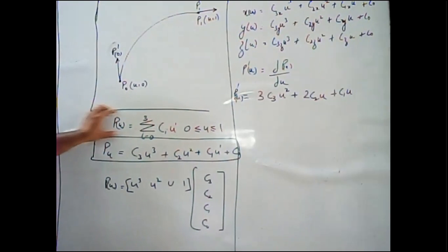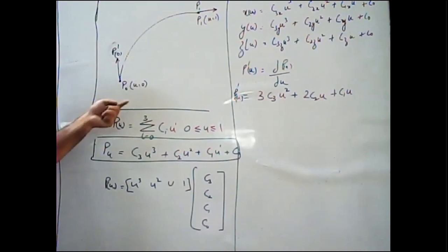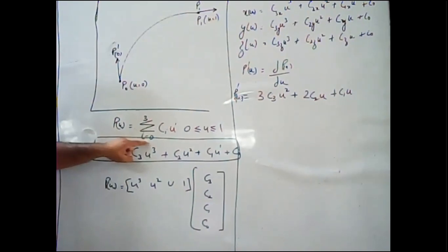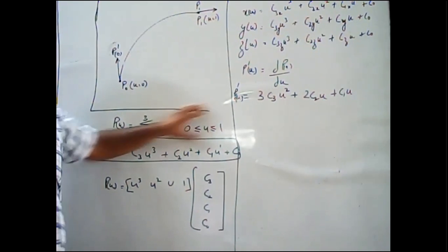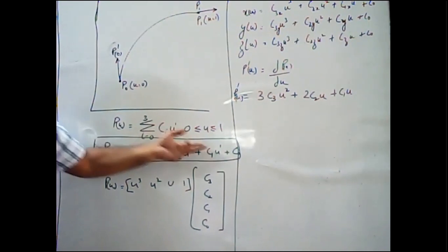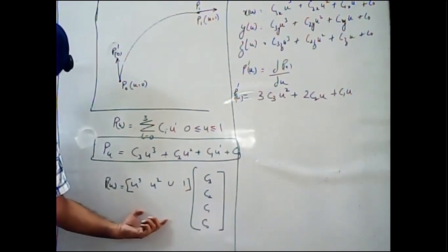So this is the governing equation. This is a cubic curve. So that curve is of order 3. Cubic curve means it is of order 3. So that is why I is equal to 0 to 3 we have put it everywhere. Then Ci ui is the governing equation of this. Then we have put the value of I equal to 3, then 2, then 1 and 0. This equation has generated. Now this equation can be written in the matrix form in this way.